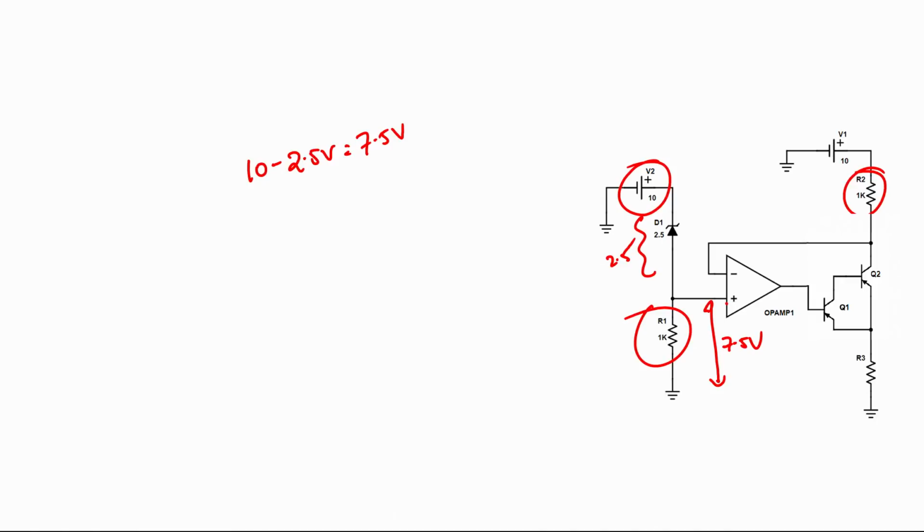For this particular diode, somewhere around 10 to 20 milliamps is the maximum current it can withstand. So the resistor R1 here is a current limiter to protect the Zener diode from damage, and since it is connected, the current flowing through will be limited.